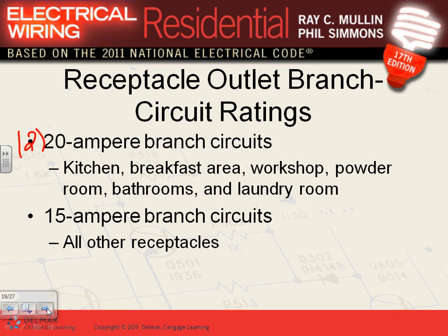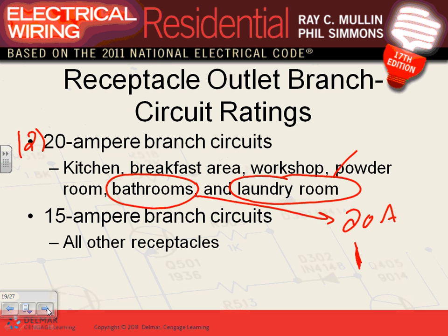The other area that also needs a 20 amp circuit is what? A 20 amp circuit for the bathroom, and the laundry room, guys, also needs a 20 amp circuit. By code, these are the only three places that you must use a 20 amp circuit. You can't get away with number 14 or a 15 amp circuit. Okay, one more time. Two here for the kitchen, all these are 20 amp, one for the laundry and one for the bathroom.